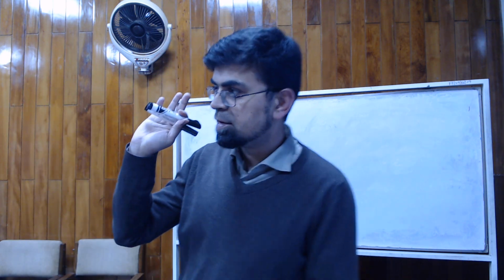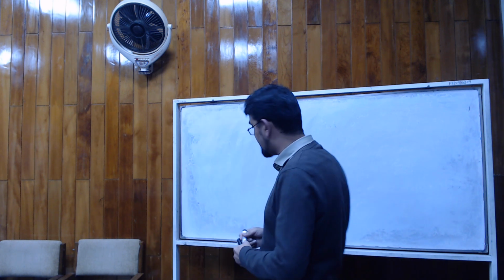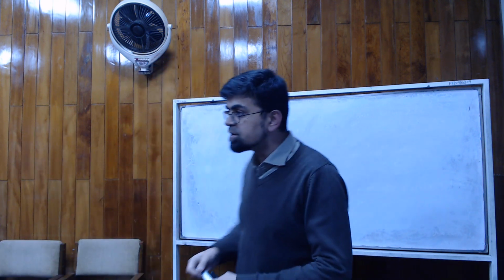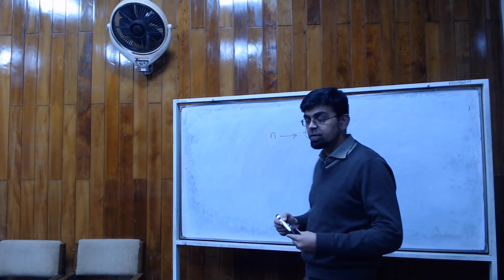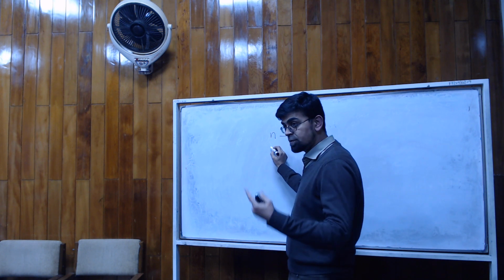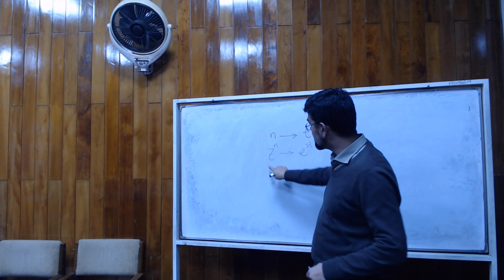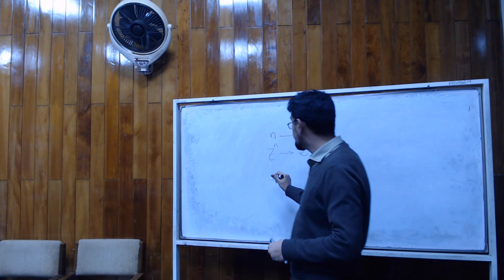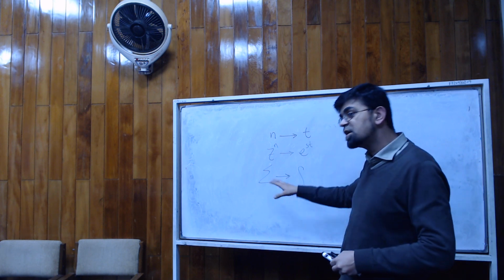Very quickly. We had closed the Z transform, and before that we did a Laplace comparison. What was the main thing? Going from discrete time to continuous, right? N became t, and z raised to power n became e raised to power st. So the eigenfunction of a DT LTI system was now this, and summation became integration. This naturally led to everything else.